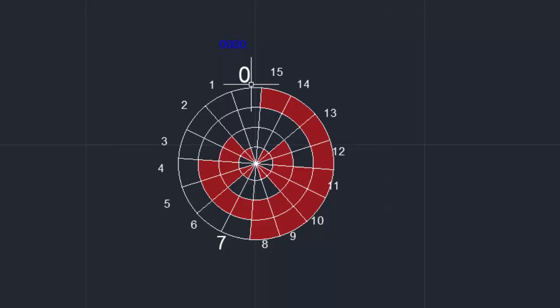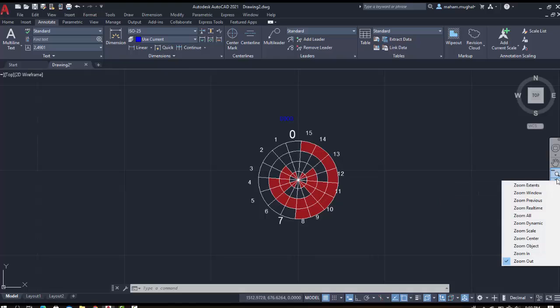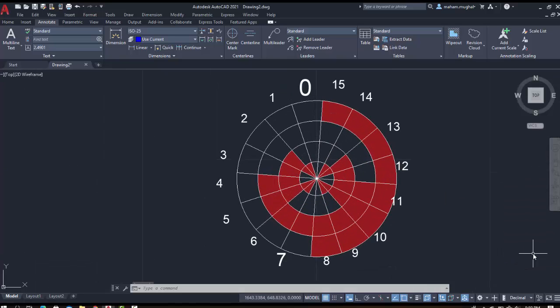But let's come back to this gray code wheel. This gray code wheel basically defines the gray codes. The colored part indicates 1, while the uncolored parts define 0. Okay, zeros and ones. It's all the game of zeros and ones. So the gray code of decimal number 0 is 0000, four times, right? So it's uncolored or non-colored. 0 0 0 and 0, right? Let me zoom it a bit. Here it is. Zoom in. Okay, that's better, I believe.